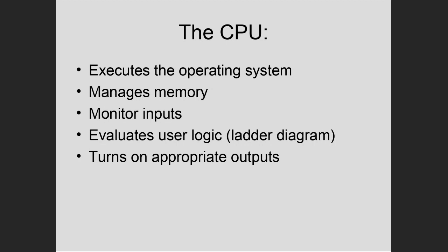You can map that screw terminal to that cell using an address. Once you do that, the state of that switch being open or closed will cause the presence of a 1 or 0 in that particular cell it's mapped to. And that's what the CPU is looking at. It's really looking at the input image table to see where the 1s and 0s are and how they're changing.